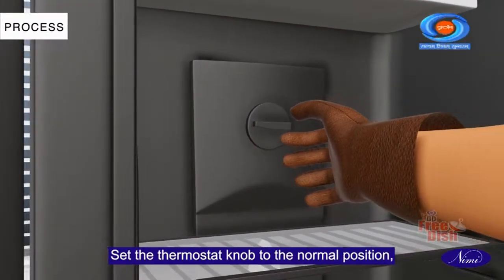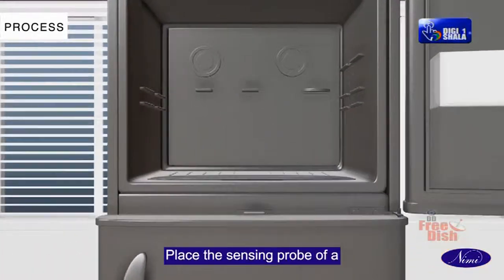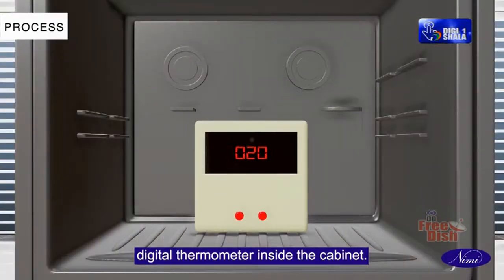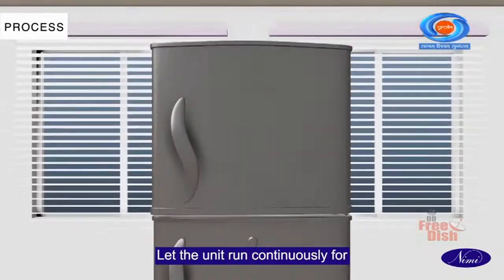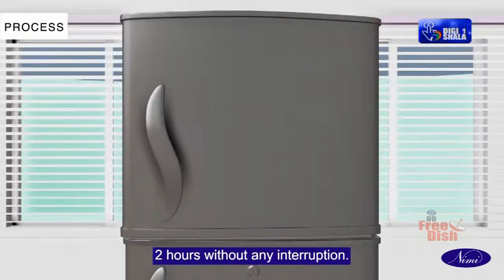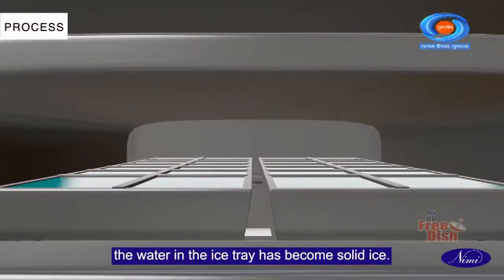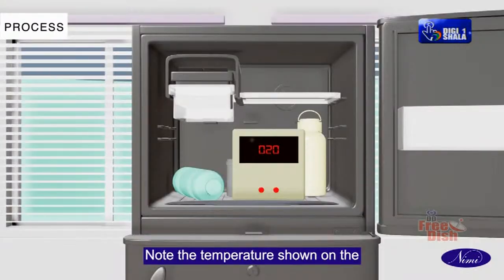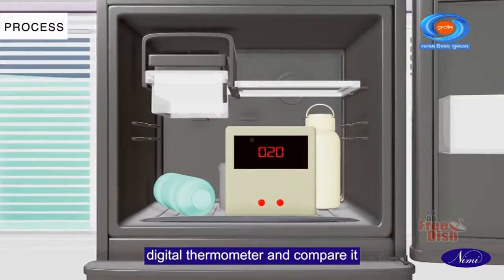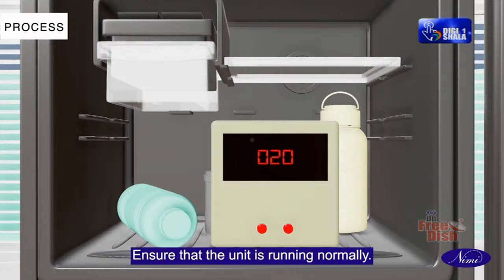Set the thermostat knob to the normal position, medium cool. Place the sensing probe of a digital thermometer inside the cabinet. Let the unit run continuously for 2 hours without any interruption. After 2 hours, open the freezer door and check if the water in the ice tray has become solid ice. Note the temperature shown on the digital thermometer and compare it with the initial temperature. Ensure that the unit is running normally.